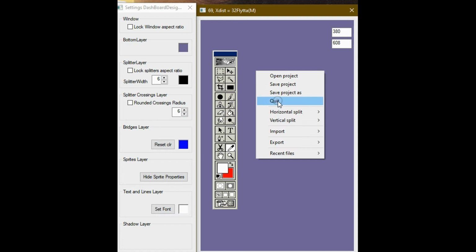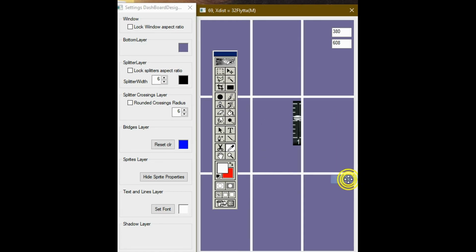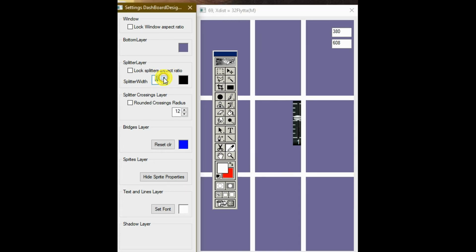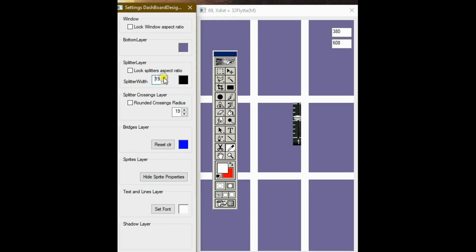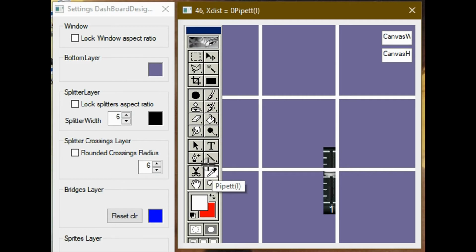And when you right-click, you can choose splitters. And splitters make out the borders for the panels. It's a faster way of working than making the panels directly. So here are 9 panels, and I control them with just 4 splitters. I can enlarge the splitters like this, so every item is intelligent, you could say. The splitters are movable, and I can even cut them with the scissors tool.